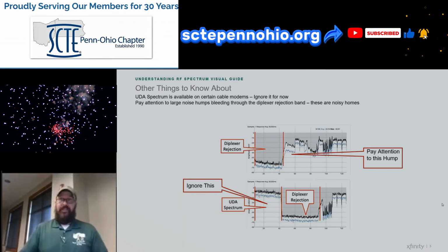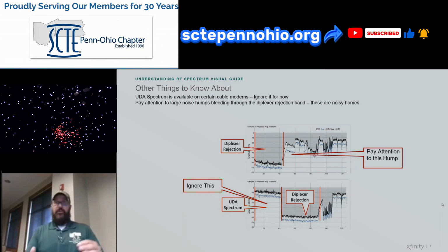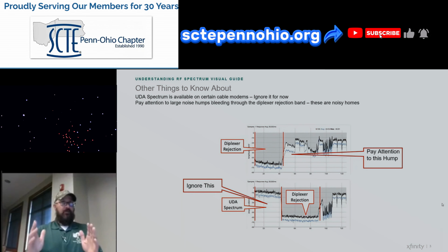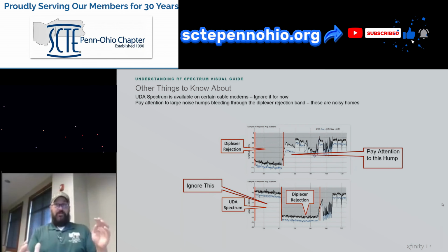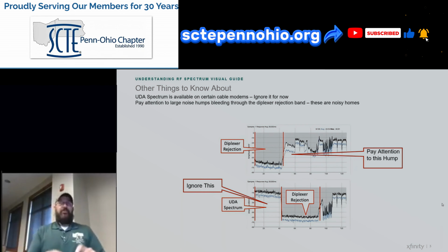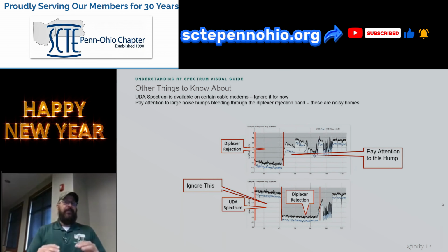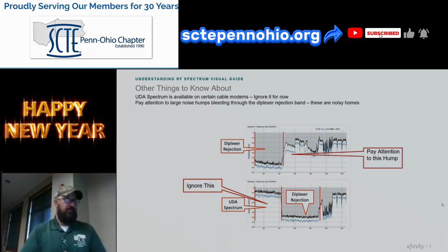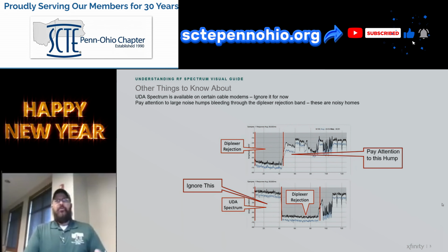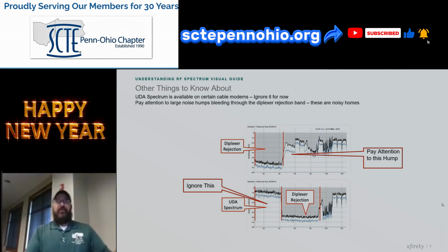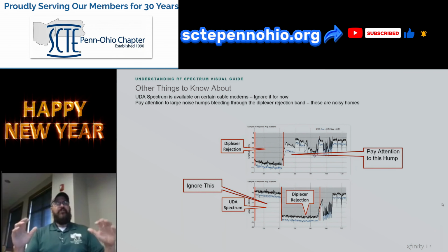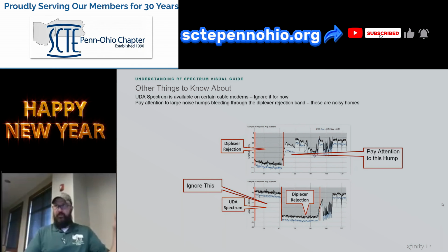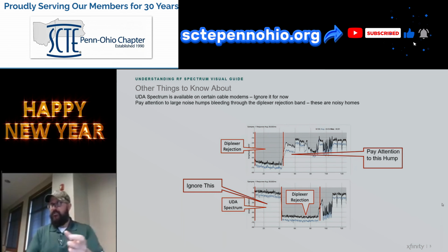Now, on the upstream, it's really looking for cavities or reflective cavities or nonlinearities that result in group delay and impairments in the channel that affect the in-channel frequency response. When we think about the upstream ICFR, it's sometimes difficult to get your head around because we're talking about tiny little 3.2, 6.4 megahertz chunks of spectrum.